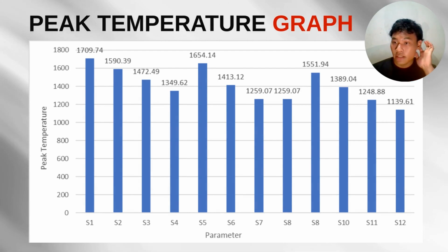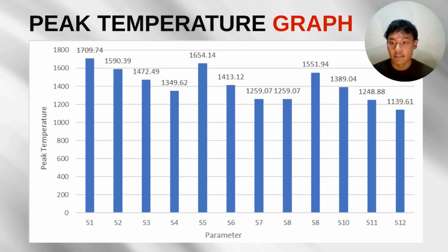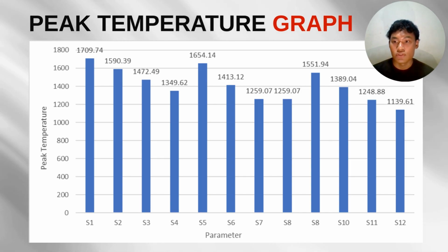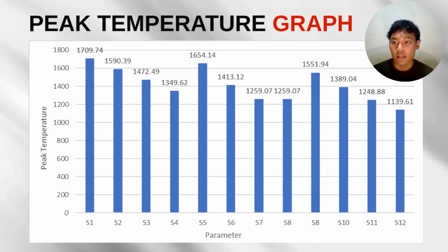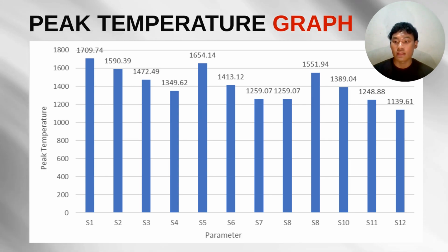You might wonder why the convex design consistently records the highest temperature compared to concave or mitre. The reason the convex design is highest is due to its geometric volume. The convex profile had an outward curving shape, which meant it required a large amount of filler material to form the weld bed. This extra mass of metal acts as a thermal heat sink, holding on to the heat from the robots longer than the thinner designs.